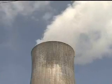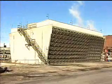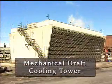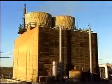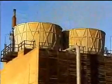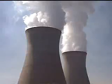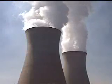Evaporation occurs when some of the heated water that's exposed to the cool air changes to vapor. The evaporation of some of the water helps cool the remaining water. There are two types of cooling towers that are generally used by power plants: mechanical draft cooling towers and natural draft cooling towers. Mechanical draft cooling towers use large fans to create airflow through the tower and thus cool the water. Natural draft or hyperbolic cooling towers have a chimney shape and do not use fans.